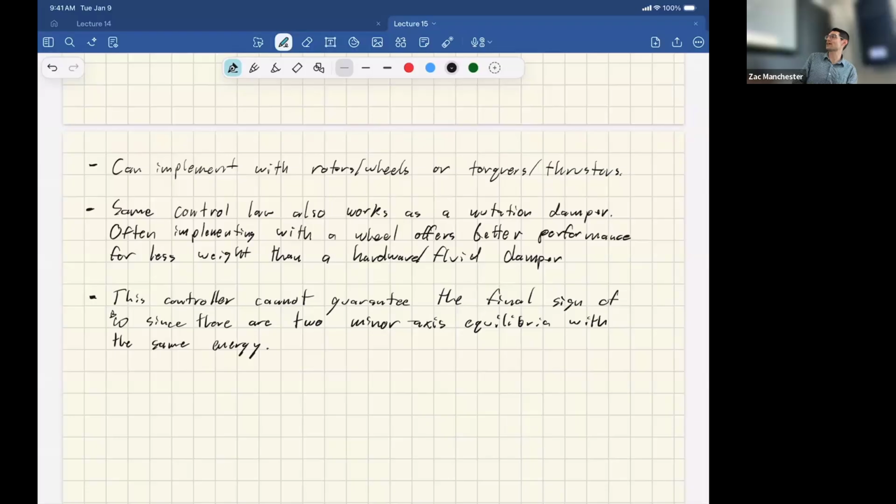The goal was to get these things to come out, say, with little solar panels, and they're pancakes, right? So we wanted to spin them up and then fling them out so that they were spin stabilized and they were major axis spinners, and their solar cells were pointed at the sun. That was the goal. These things don't have any control. We were going to use the CubeSat, which had wheels in it. We were going to point this face of the CubeSat at the sun, spin the whole CubeSat up about its minor axis, and then fling these out. If we did that right, by relying on the control system on the CubeSat mothership, we would fling these guys all out so that they were all major axis sun pointers when they were deployed.